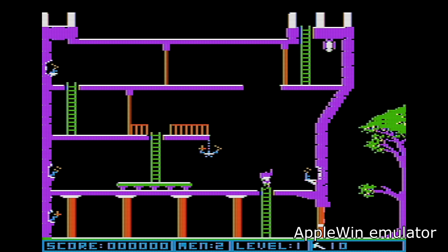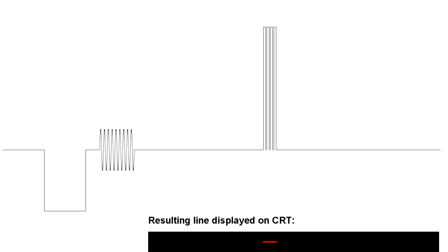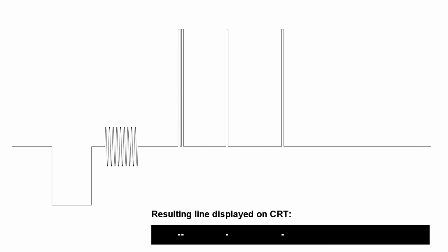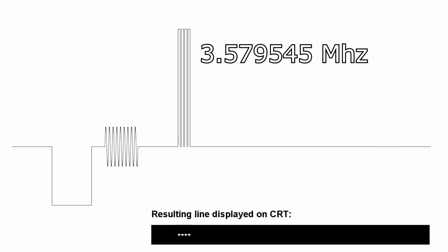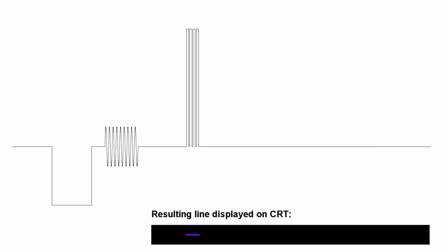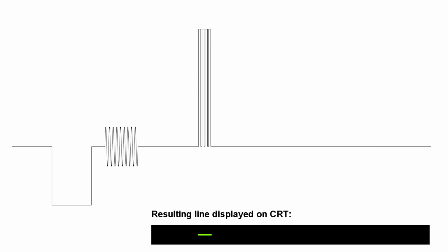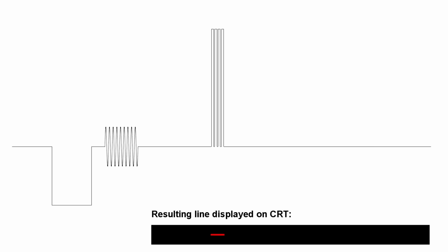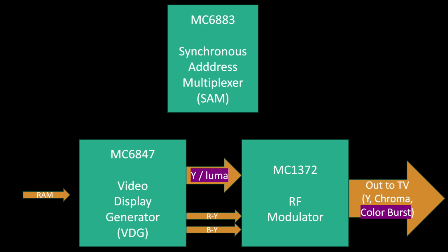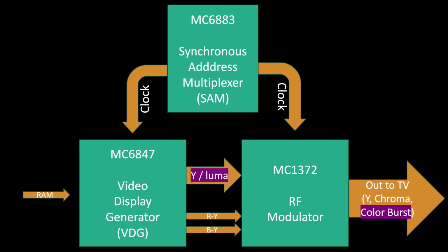And there you have it. From a cheap and sleazy TV test color bar generator, to the official Home Pong console, to the Apple II and beyond. Send a color burst signal to disable the color killer, and then send the black and white only luma signal with pixels so small that its frequency reaches 3.579545 MHz, and the position of those pixels on the screen will then result in specific reliable colors without the need to manufacture a chroma signal. Reliable, that is, except for any phase difference between color burst and luma, caused by the hardware that generates those waves using an unreliable position on the oscillator from which to base one of those signals.